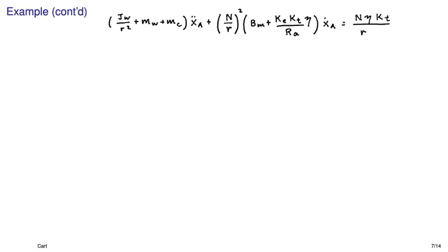So here's our equation again from the previous page because I ran out of room. And now let's just look at a couple comments. Here's our effective inertia, JW, for the wheel that, as I mentioned before, has in it the motor inertia, Jm, multiplied by n squared due to the gearbox, plus capital J. And that J is the inertia of the gearbox on its output side.